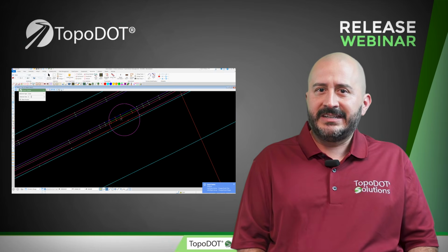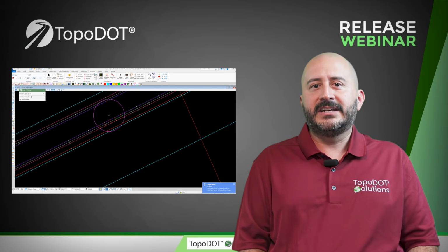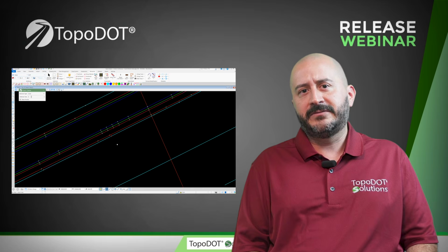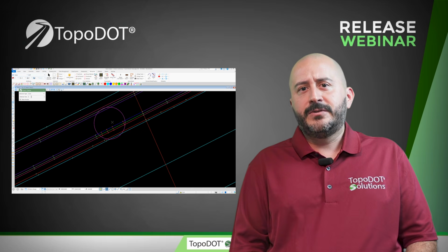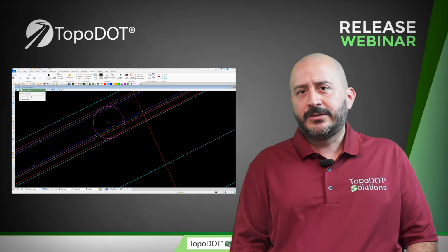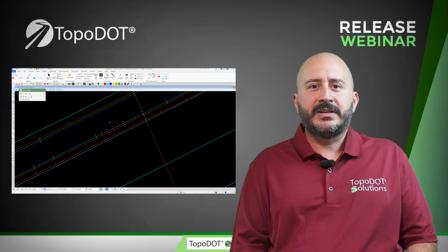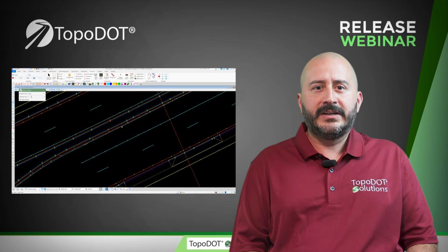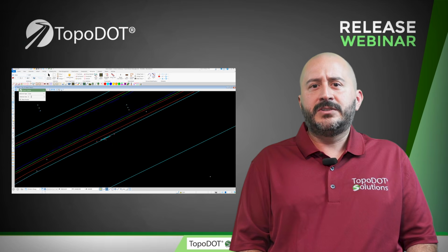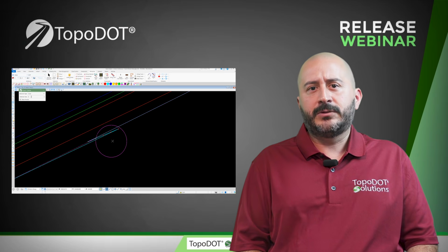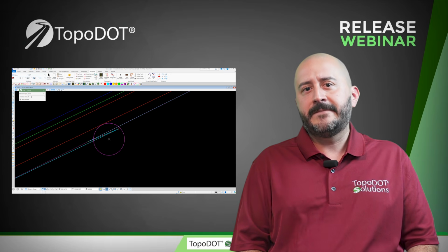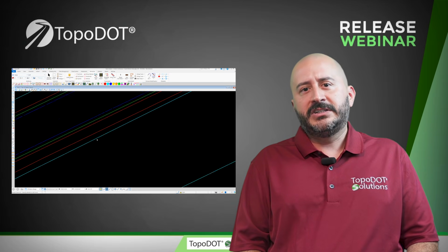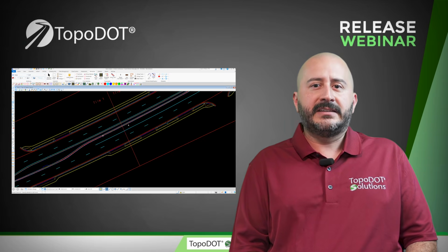In the past, cleaning up line work could mean a lot of guesswork or constantly toggling different tools just to find and delete specific vertices. Now, as you move your selection window, you'll dynamically see the location of all nearby vertices right on the screen. As those vertices enter your selection brush, they're immediately flagged in red. Even better, the tool gives you a live preview of how the line work will look before you actually delete anything. This completely removes the trial and error, ensuring that your deletions won't negatively impact the final placement of your line work.